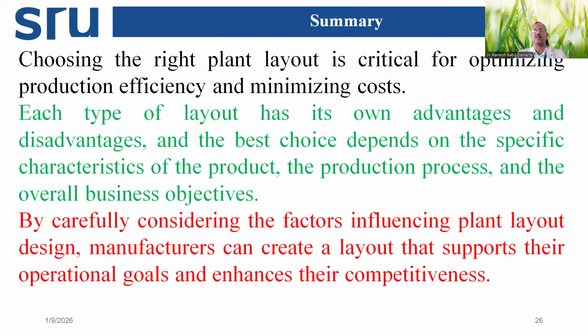So we should consider quantity and variants. Based on that, we decide mass production, batch production, or job production. So based on that, we decide product layout, process layout, cellular layout, or fixed layout. Because layout design is an expensive affair. Once it is done, a re-layout becomes unnecessary expense for the company. So one should carefully design the layout and install the machinery for efficient manufacturing operations.